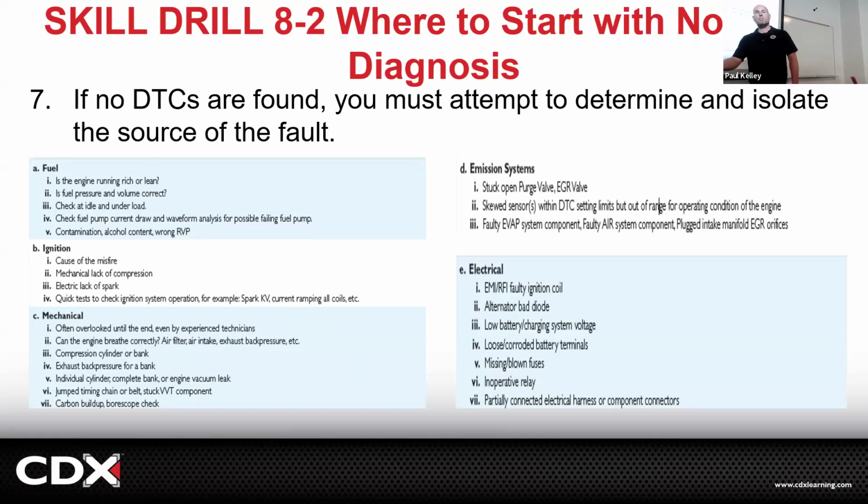Old school mechanic could smell it. Be like, oh, that's running really rich. But for me, you want to know what I'm going to do? I'm going to go in the scan tool. I'm going to look at the oxygen sensor voltage, or I'm going to look at the fuel. I can tell if it's rich or lean based on the oxygen sensor voltage. Lean is low, that'd be like 0.2 volts. Rich is high, that'd be like 0.8, 0.9, right? So I can tell right there.